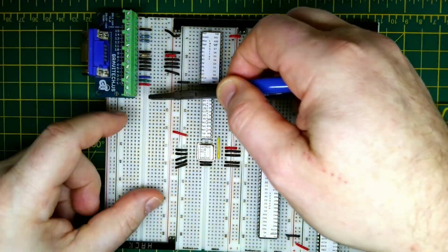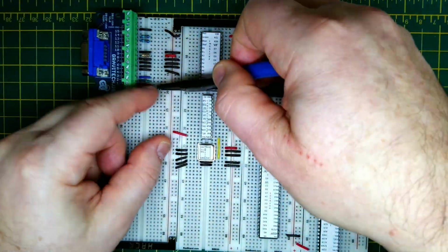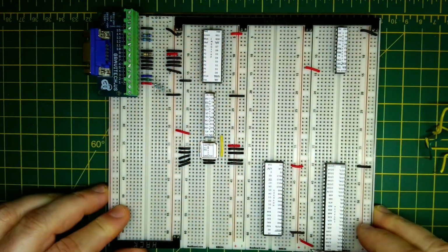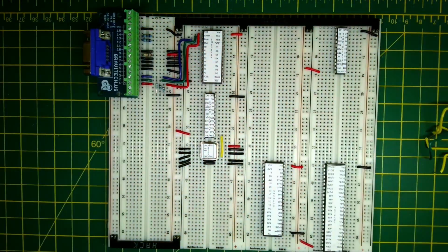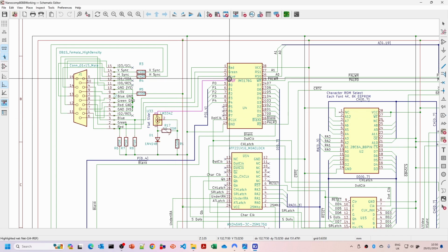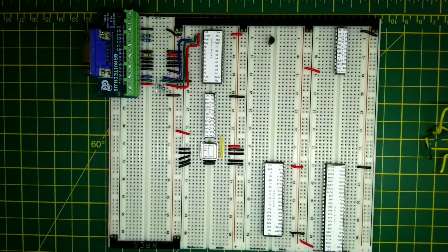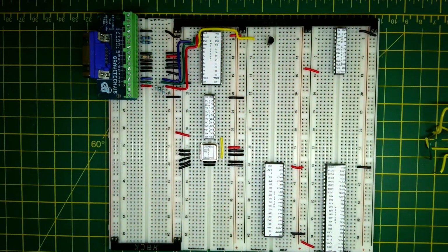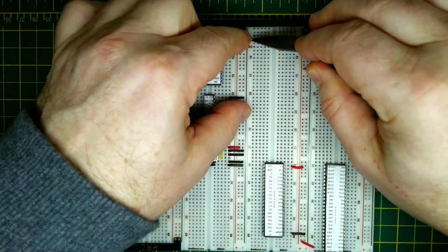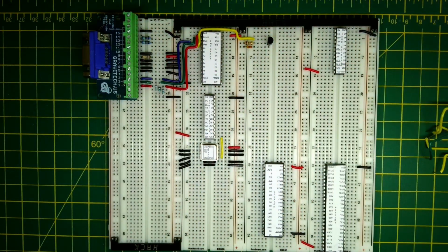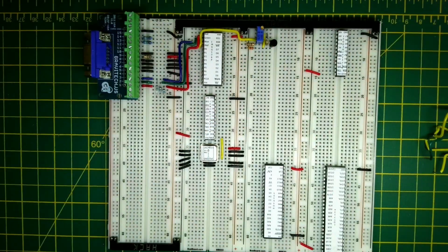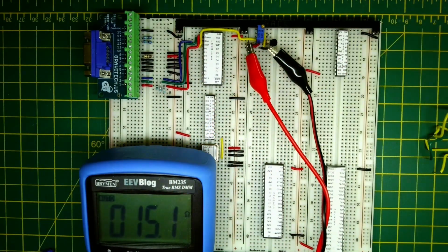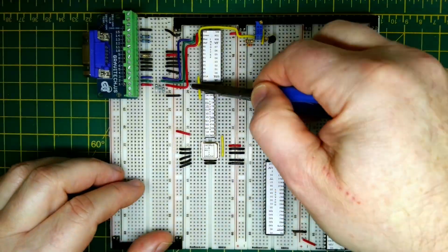We just need to wire in the ground rails there. Now we also need to add the 75 ohm resistors to ground on the outputs there. And then we're going to wire in the red, green, blue signals. Now we need to do the constant current source, discussed in the video in the nanocomp series, with the calculations for this. It needs a 15 ohm resistor to vary the current. What I've done is put a small variable potentiometer in there, and this will be nominally 15 ohms, but we can tweak it a little to increase the intensity.